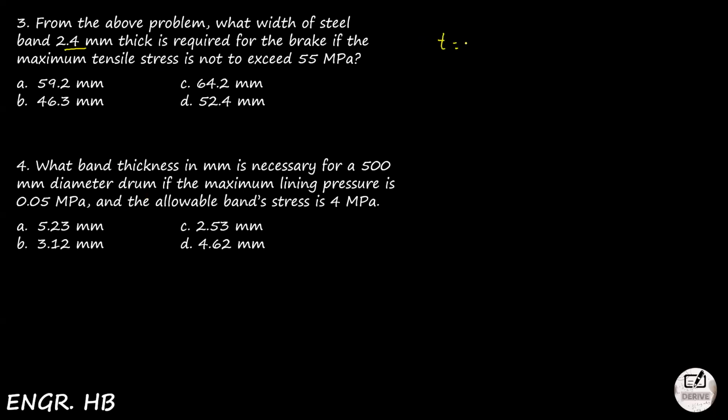Lagay na natin dito. Is required for the brake if the maximum tensile stress is not to exceed 55 megapascal. So way back on the previous slides, we all know that the maximum tensile stress is equal to F1 over width times thickness, and we are looking for the width, and we have already the thickness, we have already the maximum tensile stress. Ang kulang lang natin is F1.